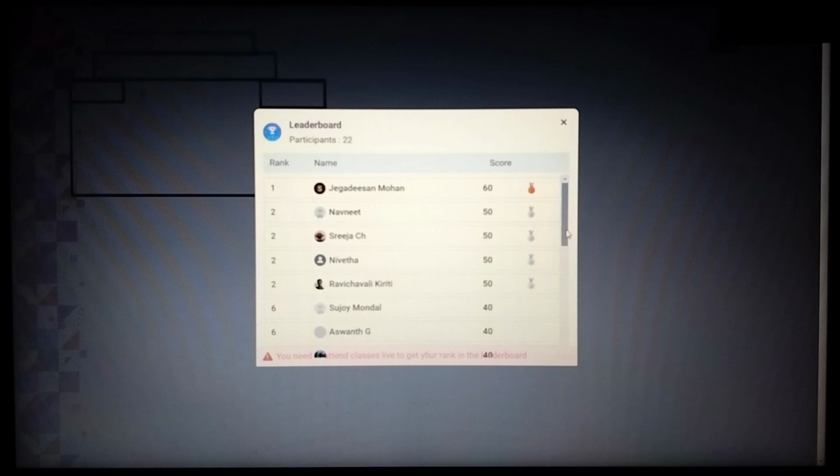Right, that is where the depletion layer increases to its maximum. Remember that concept, everyone? This is the maximum depletion layer. Maximum occurs at which point? When we are providing VGS equal to what? VT, maximum. Right. When there is a maximum, there are two capacitances: one is the oxide capacitance and one is the depletion capacitance. These two are in series.